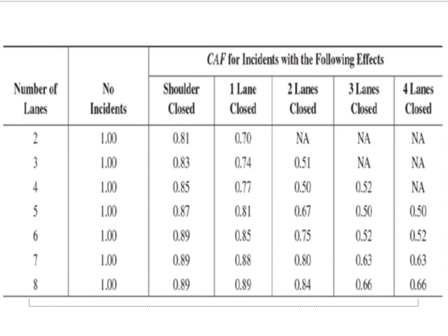You have to see how much of the road is affected by the incident. Is the shoulder only affected? Is only one lane affected? Is only two lanes affected? And so on. So the factor is according to how much part of the road is affected by the incident or the accident. If it's an accident, maybe only one lane is blocked. Or they put the car on the shoulder, so the only part blocked is the shoulder, and the rest of the road is free. So you take the factor according to that.